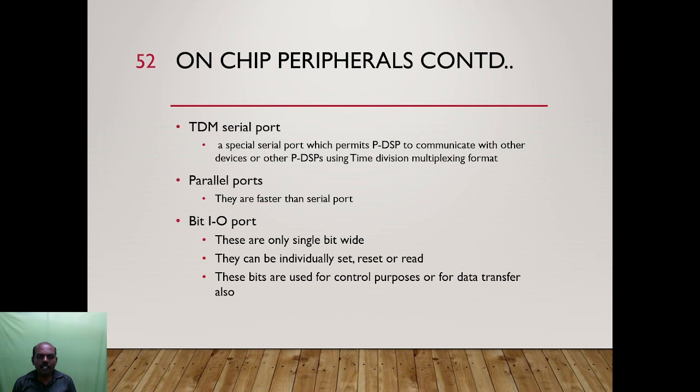TDM serial port. A special serial port which permits a programmable digital signal processor to communicate with other devices or other programmable DSPs using time division multiplexing format. Parallel ports. They are faster than serial ports. Bit IO port. These are only single bit wide. They can be individually set, reset or read. These bits are used for control purposes or for data purposes also.